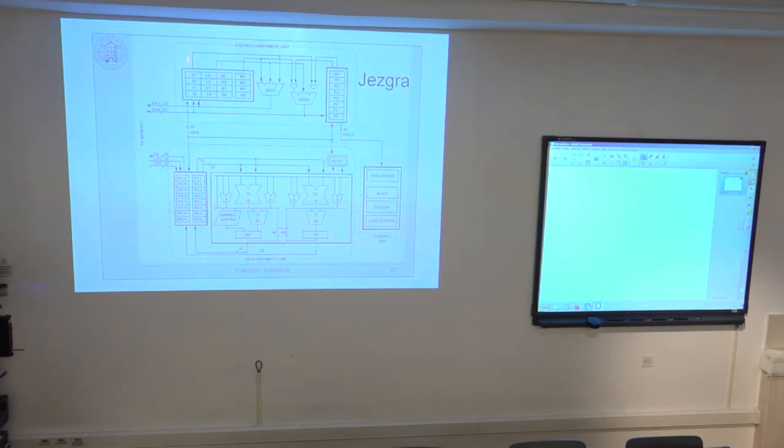I register as a pointer. L register as a modulo for the circular addressing. M register as a modification register, but it is separated from this I, L, and B because I can combine any M with any of I's. For example, I modify I1 with M2. I modify I3 with M0.